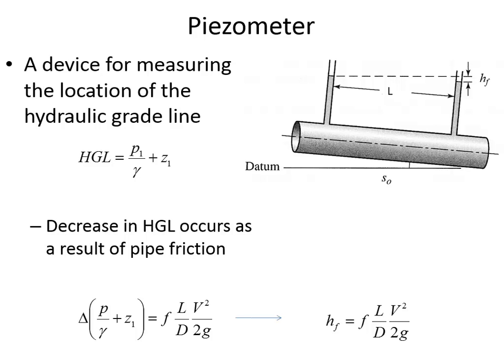And we'll use this a lot. In fact, it's our primary design equation through the closed conduit part of the course. And you remember when you're using WaterGEMS, one of the first things you'd do is go into WaterGEMS and take it out of the Manning mode or the Hazen-Williams mode, and put it into Darcy-Weisbach, because this is the more accurate way to measure energy loss.